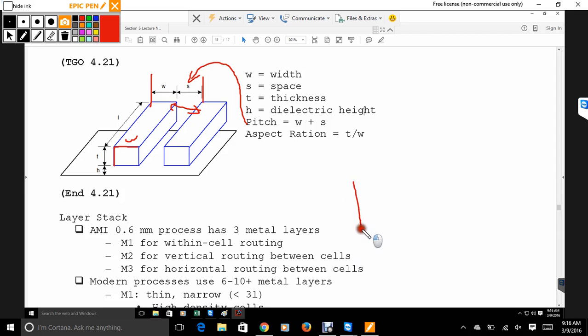And so what we're going to see down here in a second is layer stacks. So one of the solutions, we were talking about metal 1, metal 2, metal 3 before. What you're going to see in this diagram right down here is that they have a certain distance from each other, and this will answer Bo's question in more detail. So you have this dielectric in between all these different wires, so they actually run across each other in different levels.